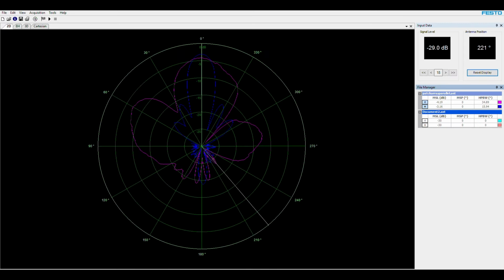Okay, right now on the screen we have H plane and E plane of our parallel fed patch array. Now we're gonna do another measurement. Let's say I hide these two so that we have an empty screen. Right now we have our series fed patch array, mounted on the mast such that we are collecting H plane. I'm just gonna start H plane right now, and then we're gonna go to E plane and compare it. To do that, let me start the RF signal.